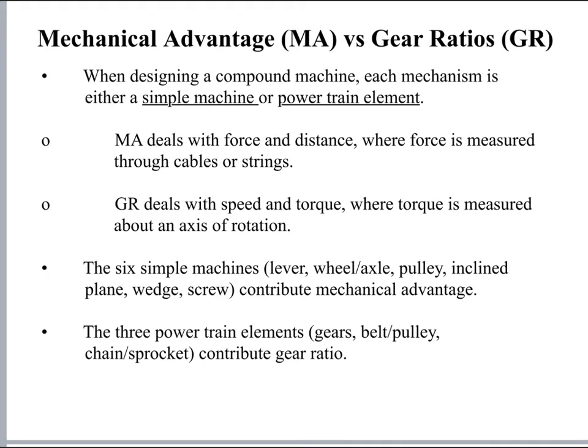Simple machines and mechanisms are, by definition, devices which transform mechanical energy into mechanical energy. On the one hand, simple machines receive as an input a single force and give out an output as a single force. These machines use mechanical advantage in order to change the point of application of that force, its direction, and its magnitude. As we saw earlier in this unit, examples of simple machines are the lever, wheel and axle, pulley, inclined plane, wedge, and screw, and no more really. These 6 are the only simple machines that are classically considered since the Renaissance period.